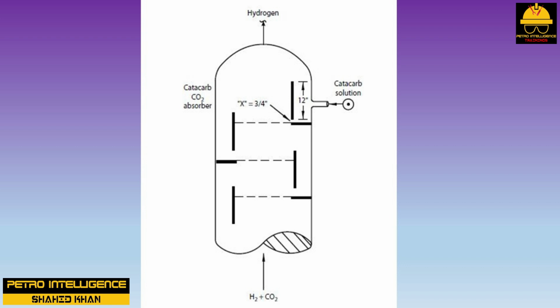The materials were ordered, and the labor force organized. However, the morning the absorber was opened, he received a call from his assistant. He informed the engineer that, "There's a plate in front of the solution inlet nozzle which is not shown in the drawings, and what do you want to do with that plate?" The engineer went there and looked at the plate. Dimension X was only about 3/4 inch. Evidently, the plate was intended as an inlet solution distributor. He calculated that the delta P, as the solution flowed underneath the plate, was about 15 inches.